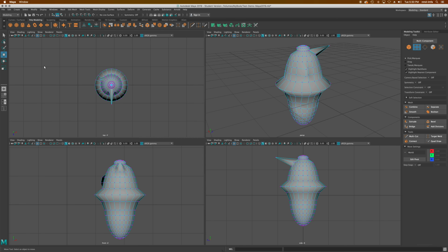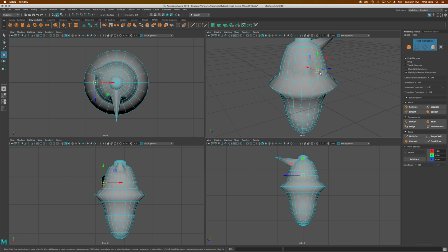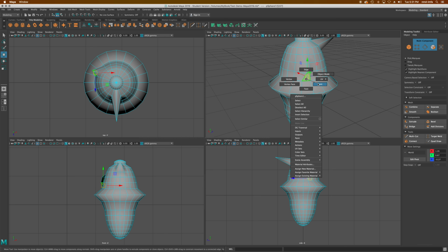So I know I spent a little bit of time there on that difference, but really spend some time with object, edge, vertex, and face mode. Now there is a multi-tool that kind of allows you to choose all of them from one. Some people like it, some people find it a little overwhelming, but you see all from one tool. I can choose an edge, I can choose a face, or I can choose a vertex. And like I said, sometimes it can be a little bit complicated to know what you're clicking on when, but other times when you're just doing quick little tweaks, it can be really, really helpful. So that's this multi-tool right here. So spend a little time right-clicking on your object, play with edge, face, vertex, object mode, and multi-tool, okay?